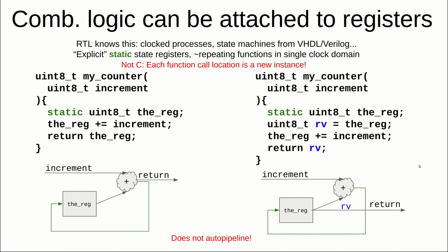So I had come from this place where I had combinatorial logic and was doing autopipelining, and I had the function's body giving me a data flow graph, and I needed some kind of C concept that would map to this: the function is occurring multiple times, called multiple times, you might say, but there's some kind of state that's sticking around. Static local variables seem like a natural fit. So you could picture these functions as running multiple times, each time being a tick of the clock. It's all synchronous here, with rising edges in the back.